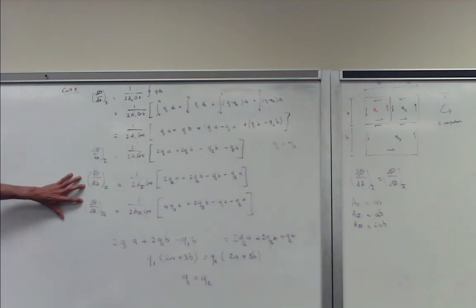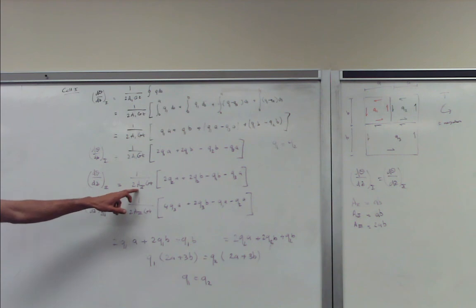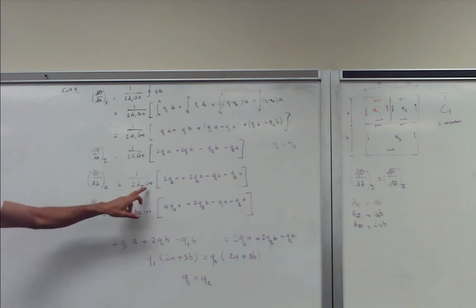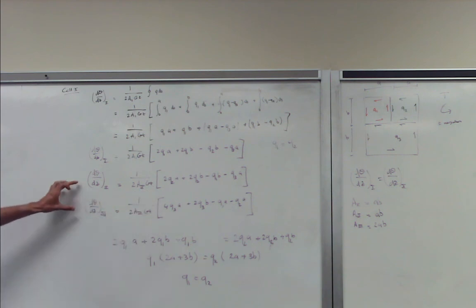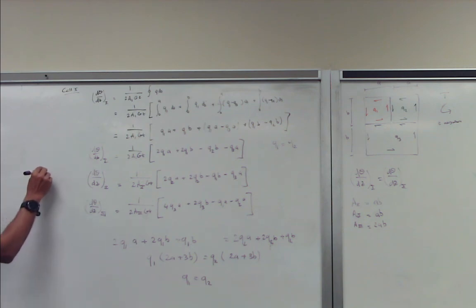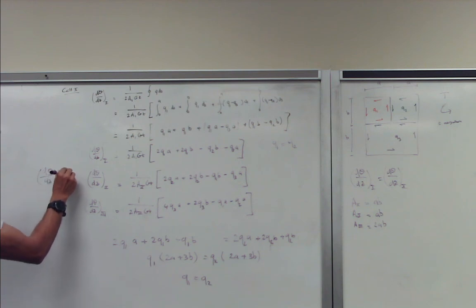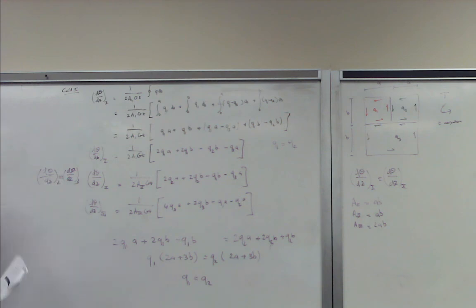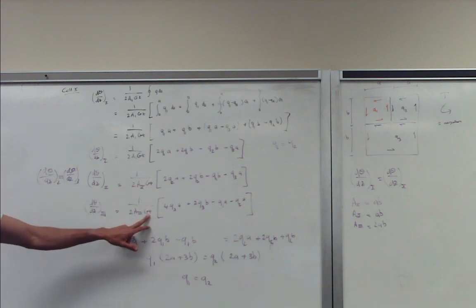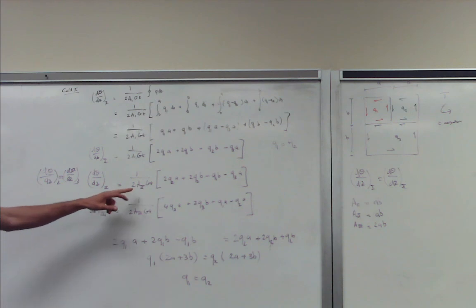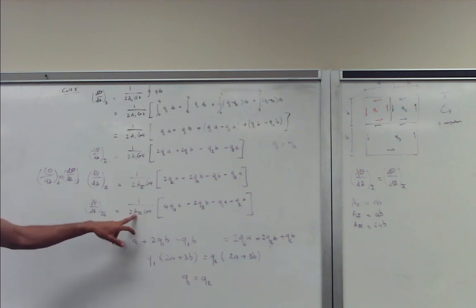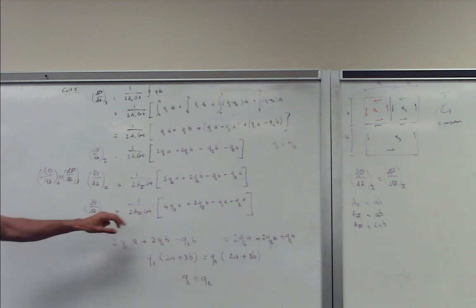Then we can set up a similar equation here. In this case, the G and T will drop out. If you say the rate of twist d theta dz for cell 2 is equal to that for cell 3, since we have the same shear modulus and same thickness, they will drop out. However, the area 2 is AB and the area 3 is 2AB. So be careful with that. The areas do not drop out in this case.